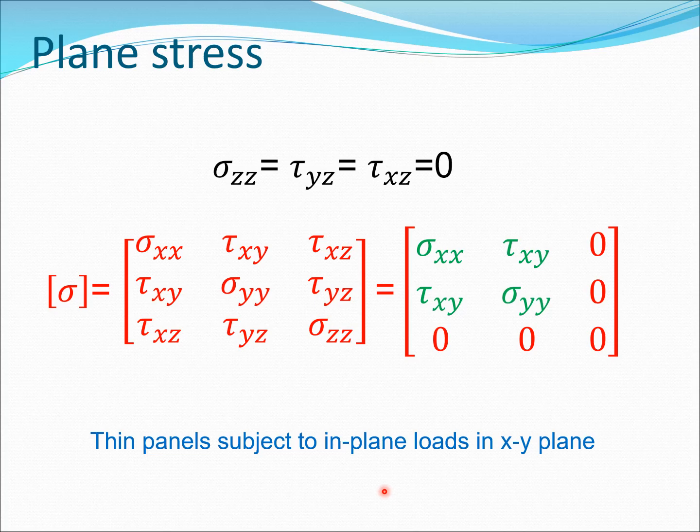The plane stress case is actually quite useful, though structures are not really completely in the plane stress situation because some remnants of these stresses are always there. But what we are assuming here is that these stresses may be very small and therefore negligible. This is one of those engineering decisions which is made so that the calculation becomes simple.